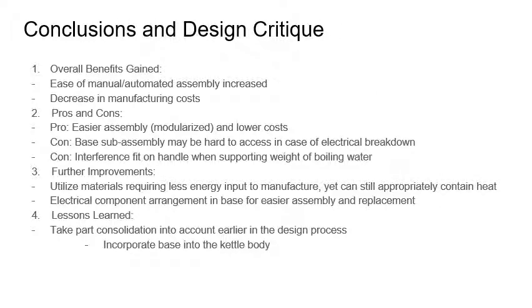The DFMA analysis and redesign was overall a successful endeavor. The redesign saw improvements in ease of assembly and decrease in costs. Some cons we saw with our product was the difficulty in accessing the base subassembly once it's been assembled in order to fix electrical components that may be damaged. The snap fit between the handle and kettle body is also possibly not as reliable as the original design.